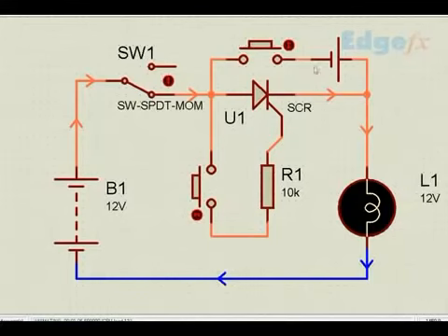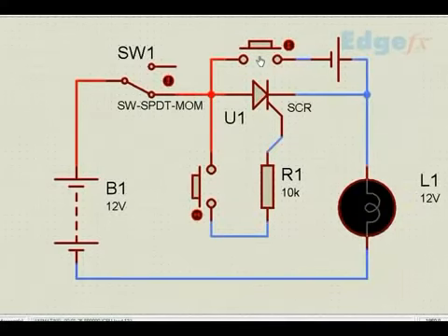In this conducting stage, it can also be switched off. How? I apply a negative voltage. I have taken a one cell battery which is 1.5 volts. When the current is flowing, this side is positive, this side is negative. Now if I apply a voltage in the reverse direction, this side positive and this side negative, to this switch, what will happen? This SCR will perforce go to off. Now let's see that. You see, though this path was there, the SCR has again gone out of conduction. Would you like to see it again? Let's see this.